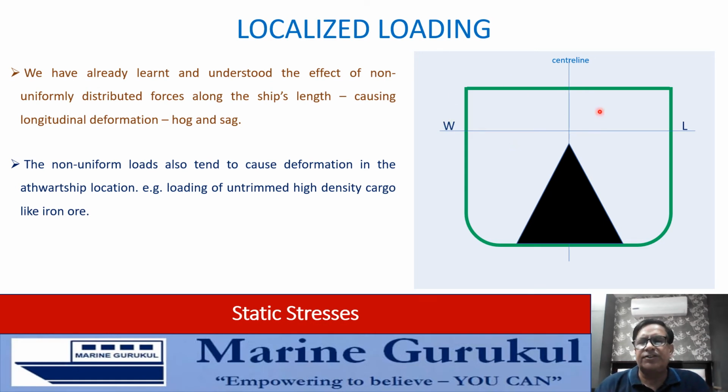So in this cross-sectional view, we can divide it into three parts: one close to the center line and one on each of its sides. Now, as you can see in this cross-sectional view, if the buoyancy in all the three sections is assumed to be the same, then I'm sure you'll agree that in this part, the weight will fall short of buoyancy. Why? Because the buoyancy would be corresponding to the complete weight.